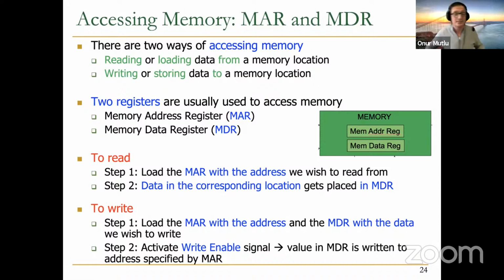And this is all dictated by the clock cycle that you decide to have in your processor, as we will see also. So all of this should be able to happen within one clock cycle, assuming you have a one clock cycle access memory. We will later break that assumption. We will make memory multiple access cycles, multiple clock cycles, because it just takes too long to access large memories. But don't worry about that for now.